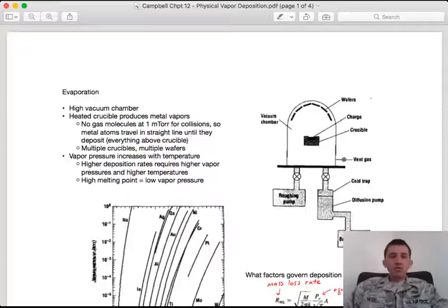And then you are coating with a metal that you heat up to increase its vapor pressure. And so you generate more of these liberated metal atoms from the surface that we use to coat our targets with. Okay, so you're at low pressure, and what you want are the atoms in the atmosphere to be the metal atoms that you want to coat with, and so you need to raise the vapor pressure of that particular metal.